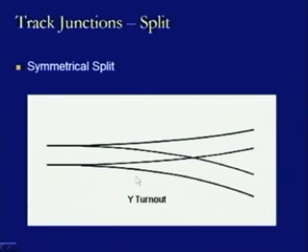Here we have one pair of points or switches provided at this location, and because it is symmetrical in nature, there will be only one crossing provided here. So, there is one crossing, one pair of wing rails, one pair of jack rails, and two pairs of curved lead rails in the contrary flexure direction.